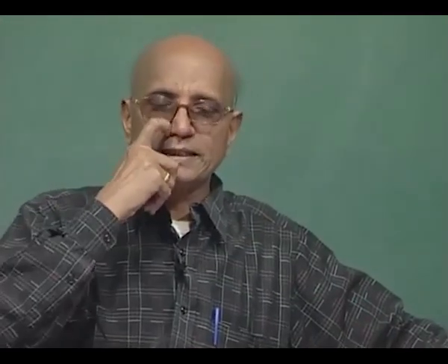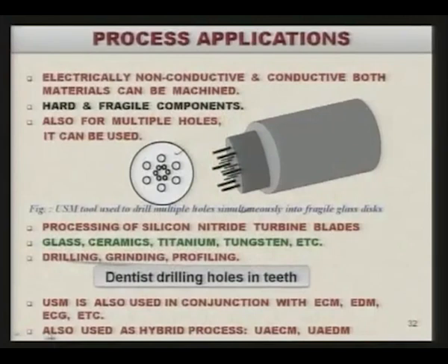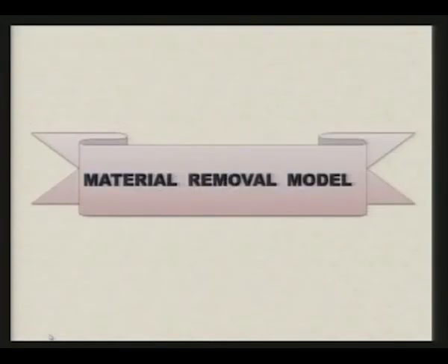What we are really doing in case of ultrasonic assistance is that the tool is vibrated at ultrasonic frequency. Once the tool is vibrating, say in case of ECM, then the removal of the electrolyte becomes much more effective than without ultrasonic vibration. So, it is found that in case of ECM and EDM, the ultrasonic has improved the performance of the process to a large extent. Also it is used as a hybrid process like ultrasonic assisted ECM, ultrasonic assisted EDM.